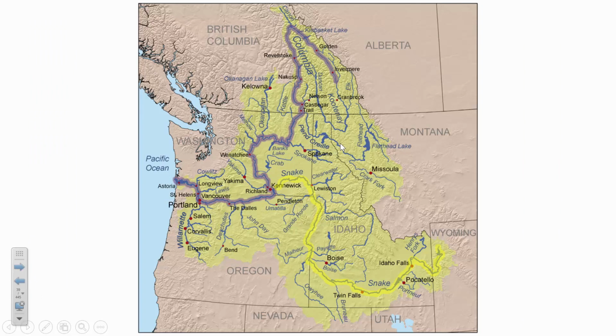One of the reasons that spillway elevation is so important is that there is a lot of land upstream that is going to be affected by what spillway elevation you choose. You can think of the spillway elevation as the maximum height that the water level is going to be in the reservoir that's upstream of a dam.